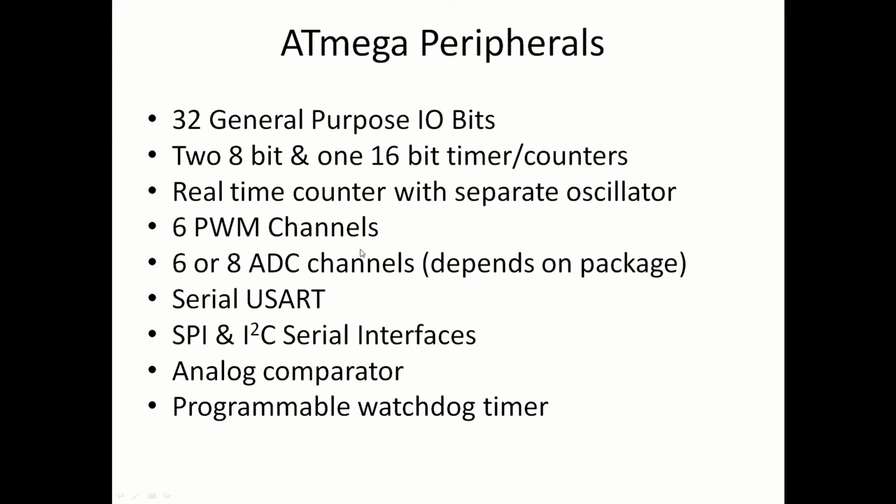It has an inbuilt A to D converter with up to 8 channels. There are serial ports, a universal asynchronous receiver transmitter, a serial peripheral interface, and the I2C serial interface, which is a synchronous communication. There is an analog comparator and watchdog timers.